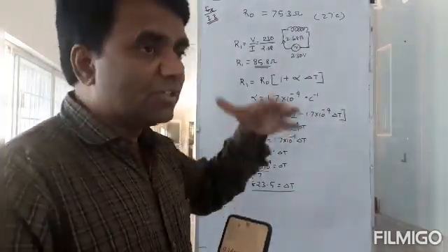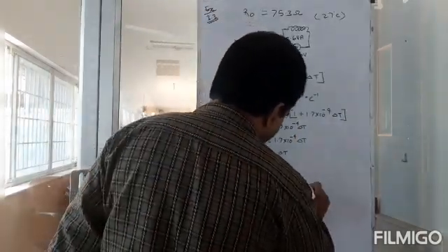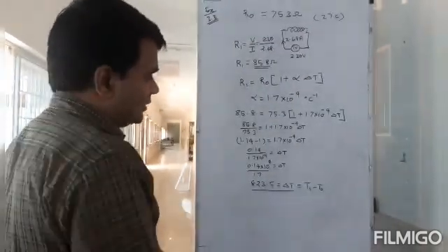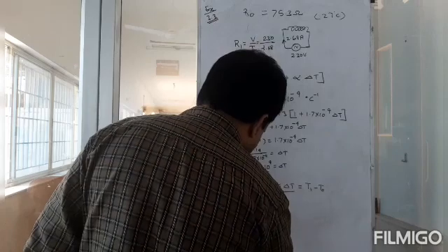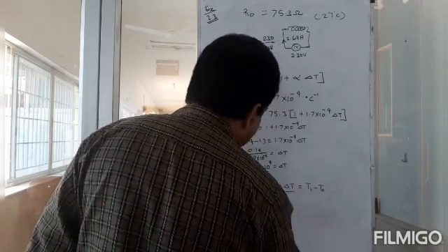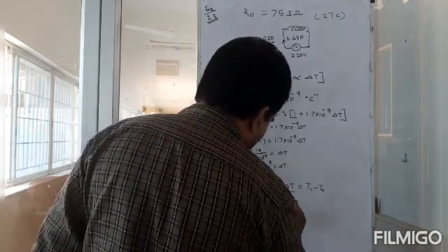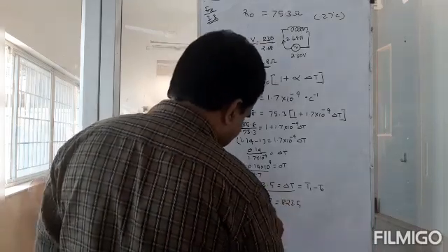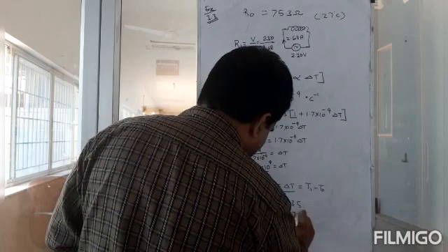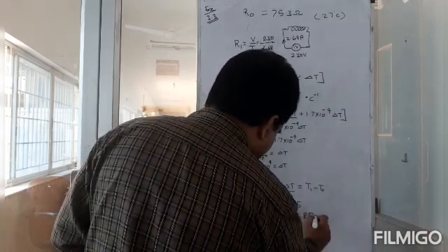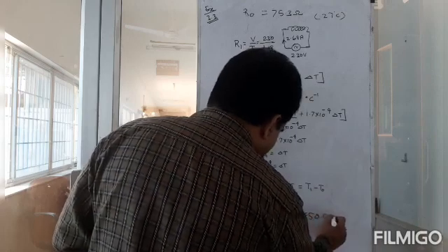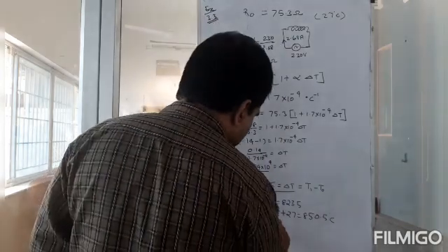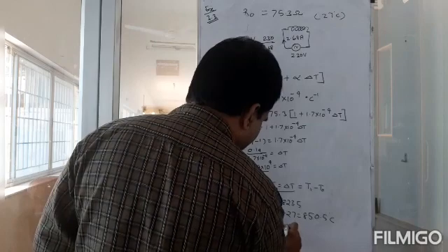But what is the temperature? What is the original temperature? So what is delta T first of all? Delta T is final T1 minus initial T0. T0 is 27 degrees Celsius. So delta T is equal to T1 minus 27 degrees Celsius, which was equal to 823.5 degrees Celsius. So now T1 is equal to 823.5 plus 27, that will give me 850.5 degrees Celsius. So the temperature of this coil, this nichrome heating element, now is 850.5 degrees Celsius.